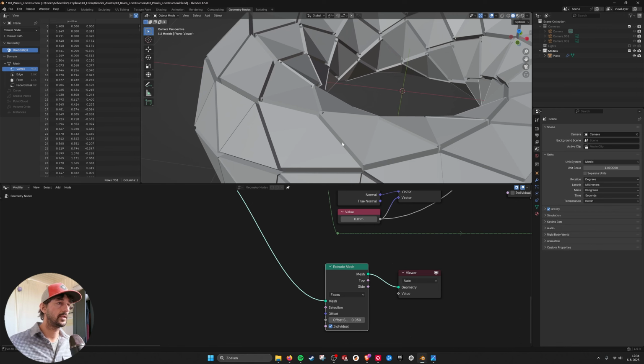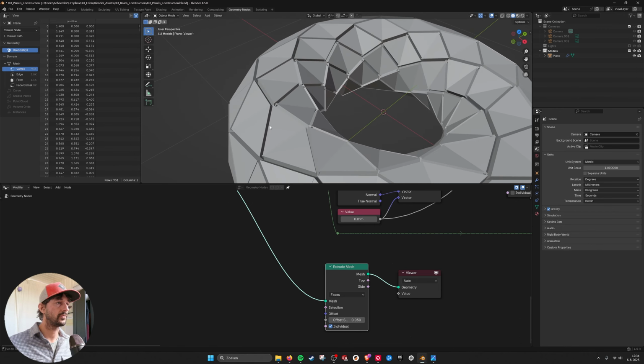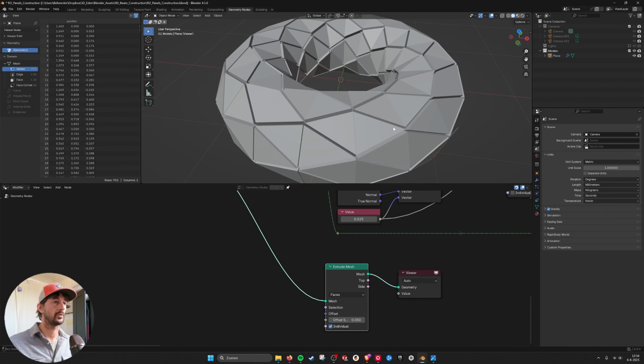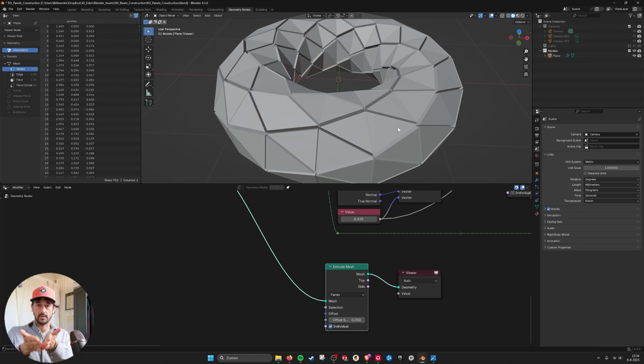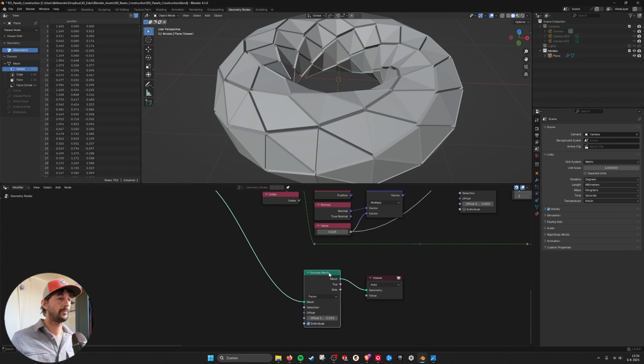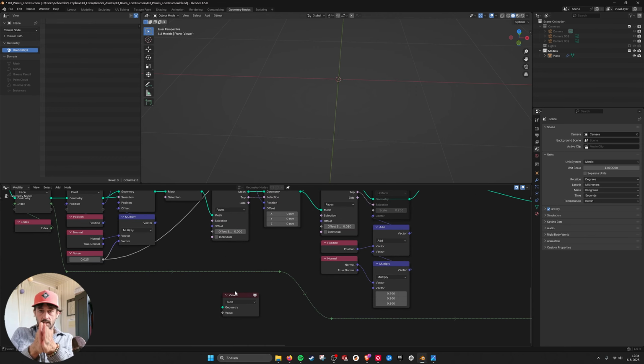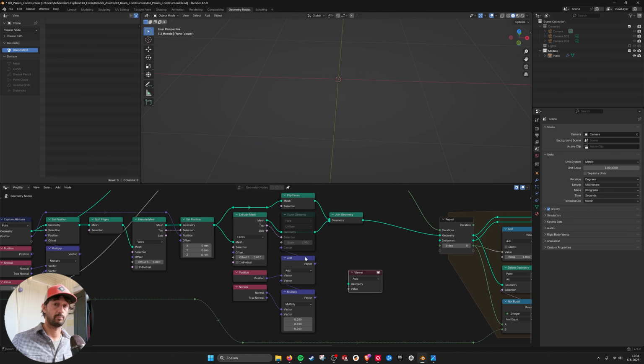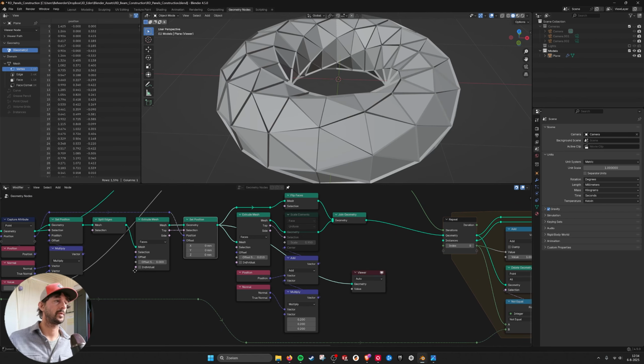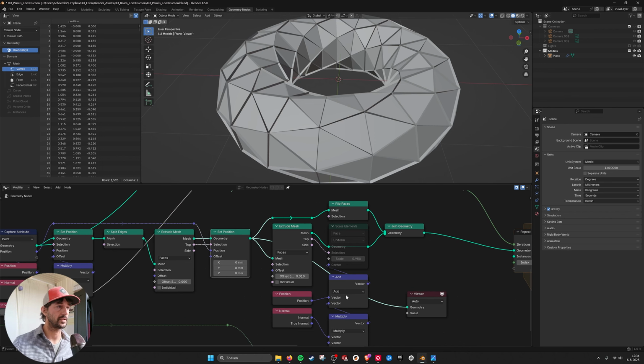These inner faces must be aligned, or else you get panels that are not connected. There's a V shape between them, or they are inverted and they pass through each other. So I needed these faces to be exactly aligned, because they are going to be separate panels bolted together, so you don't want any gaps. And that's what's happening here by setting the position.